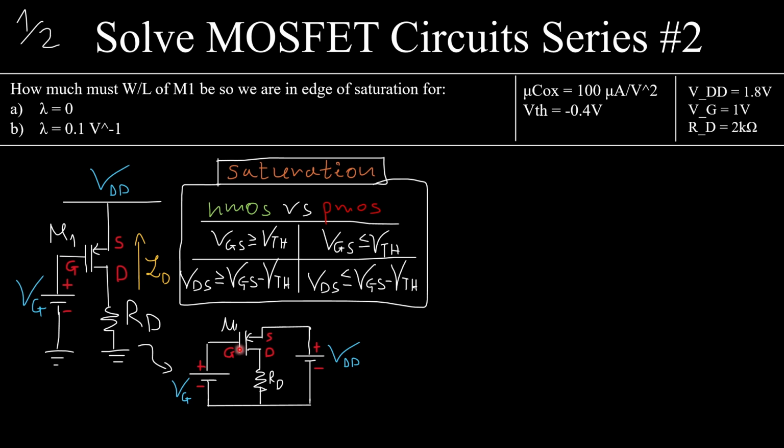Now this circuit is nothing but this circuit, all right? I put my transistor over here. I have my two batteries over here with a negative terminal connected all the way to the ground. The ground is nothing but a common terminal with 0 voltage. For the pMOS, the source is at the point with higher voltage over here.